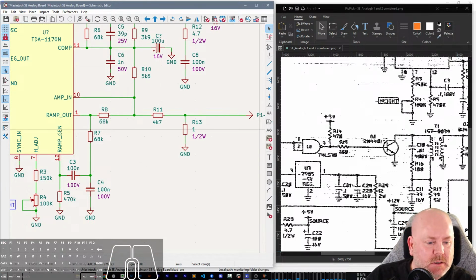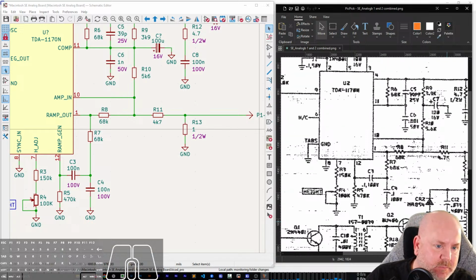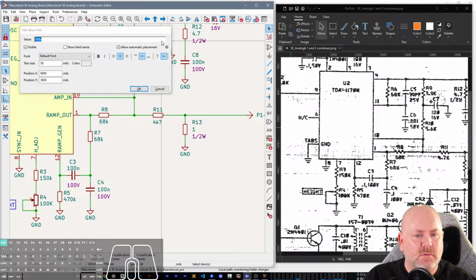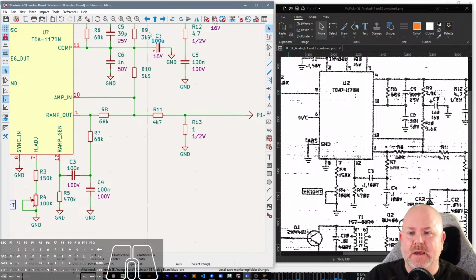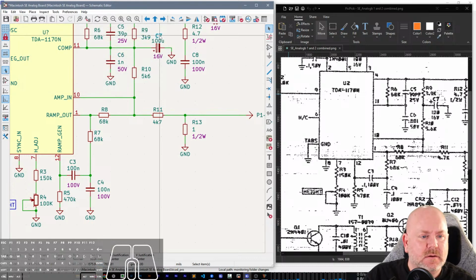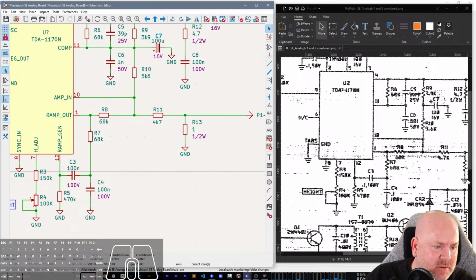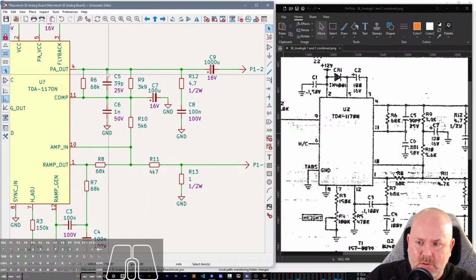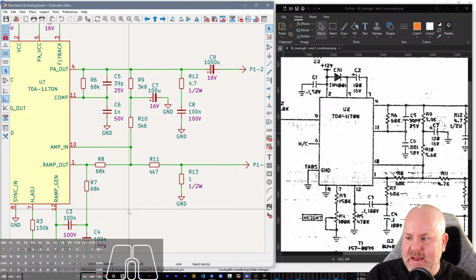We lost our symbol up here. What was our designator? What was comp, the signal? No, yeah, out of the comp, out of pin 11, C6. And that was a 100 nano, not mic. What in the world? Oh, okay, that's C7. Wait, something's wrong. This isn't right. Hold on. For this, there should not be a connection here, because it should be R9, R10, C7. Okay. Got it.